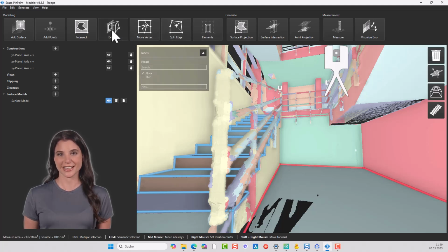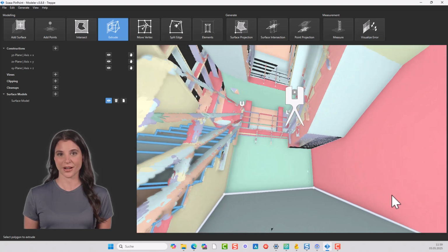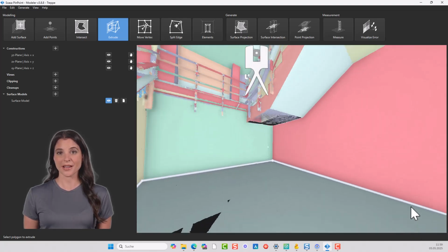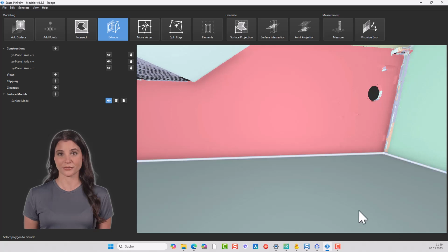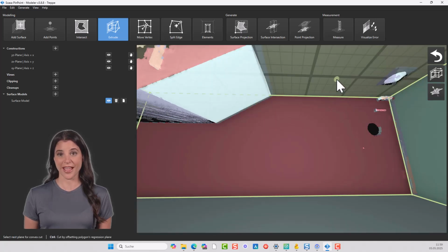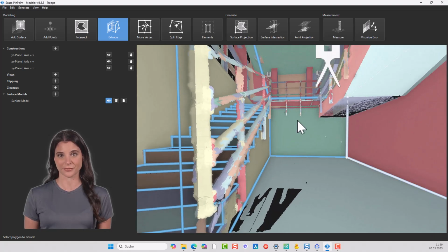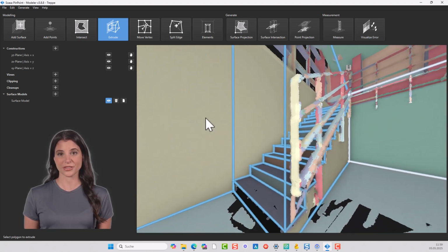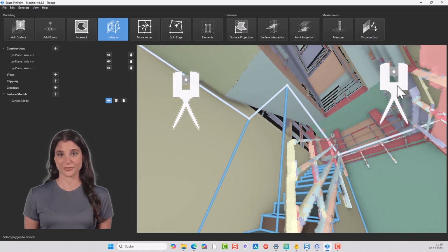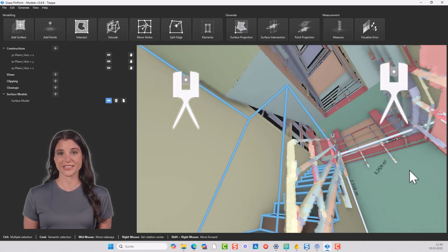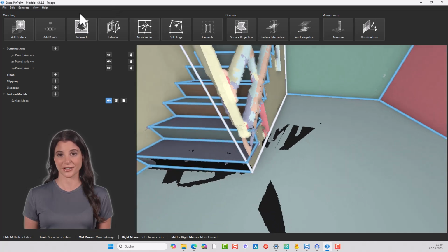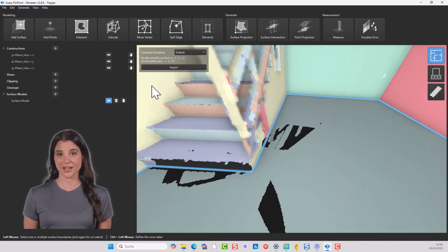I'll pull it up to the second ceiling, even if that's incorrect on the right side. My goal is just to show the floor plan in relation to the staircase. For that, I need the larger polygon. Now we basically have the 3D model. Exit the extrude mode with Escape, then go back to Generate Floor Plan. Click it again, select Stairs, and select the staircase separately, so each element is selected individually.